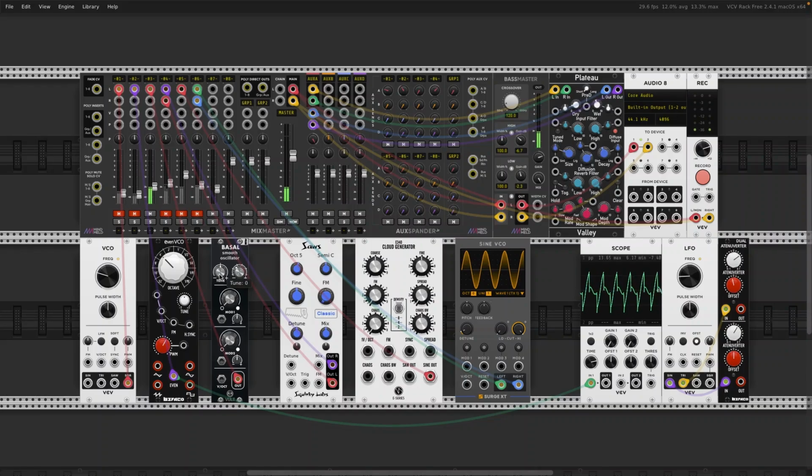But you also can fine-tune it, and here you can go up and down 3 octaves, whereas here within an octave you can fine-tune it. And once we have our note, of course you could patch in some voltage here to the pitch input, and you don't have to turn these knobs, but you could still change the octave. But the interesting thing is these two modulations, and what they do.